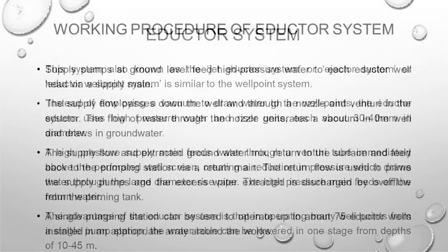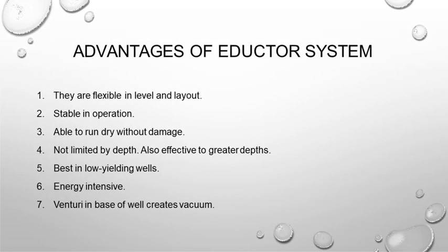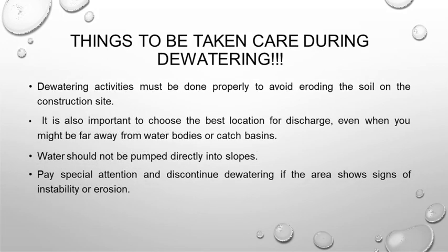One more system is also used for the dewatering purpose. You can see some of the advantages of this system. They are flexible in level and layout, stable in operation, able to run dry without damage, and not limited by depth. Some of the advantages of this system.